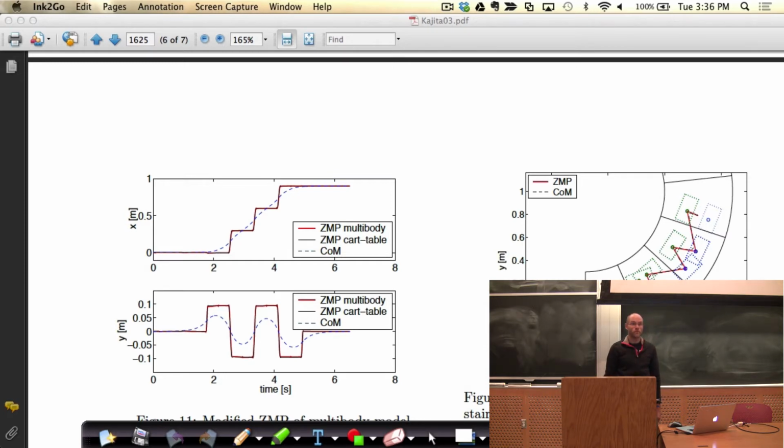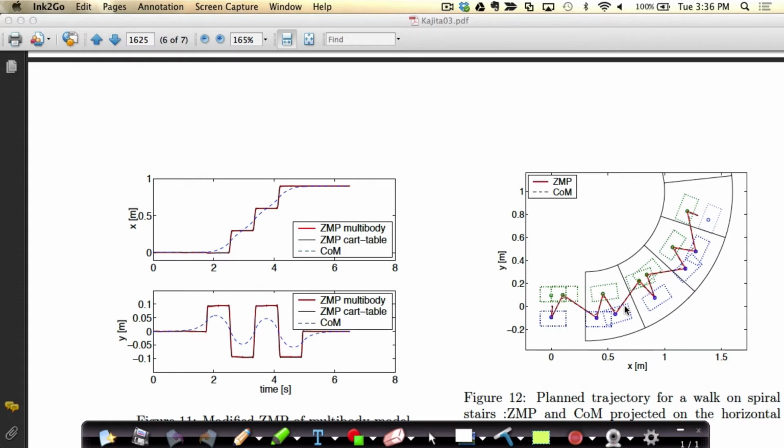Yeah. So do they know the model of the terrain? Say it again. Do they model it? Yep. The terrain is known. You choose your footsteps ahead. Hard problem. We haven't told you a solution for that yet. But if I put some down, and I just hand prescribe the center of pressure trajectory, then I could solve the center of mass trajectory and solve it very fast.